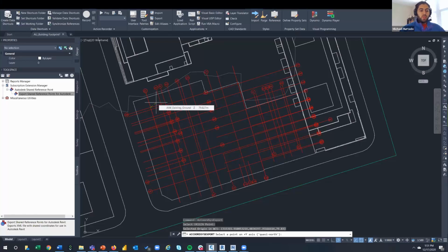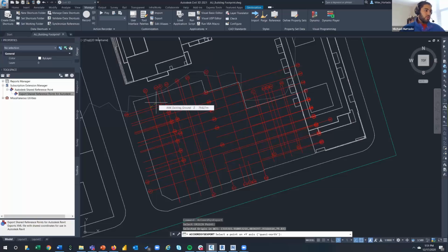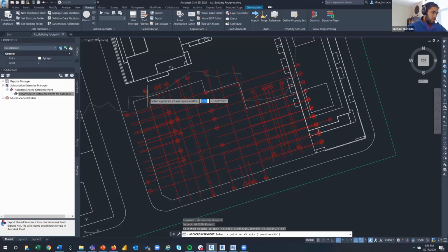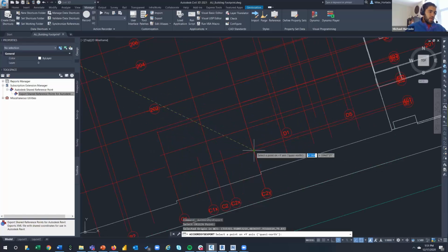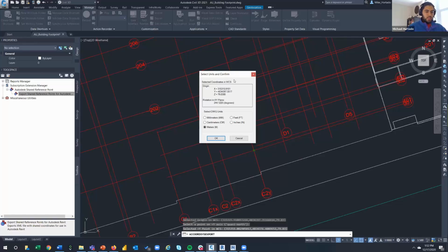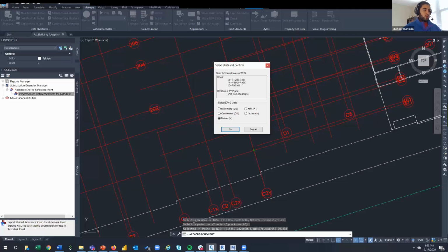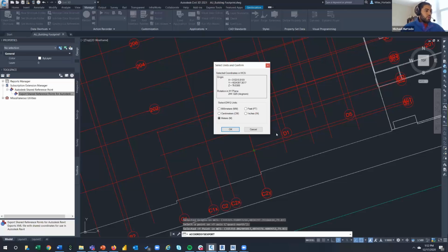The trick here is to make sure that the point is at the same elevation as your first point. That's why a lot of folks will run into this and instantly drop the tool because it's like, oh, it's not working. The second point that you're picking has to be at the same elevation. Since it's a grid, it's all flat for me, all at elevation 0. I'm going to select any of the other points, just this one. It's just a habit. I think Nick mentioned it. Basically what the tool does is it writes out this XYZ information and then the rotation for your XY plane. So you will get an XML file that Civil writes out for the location of your line work here.